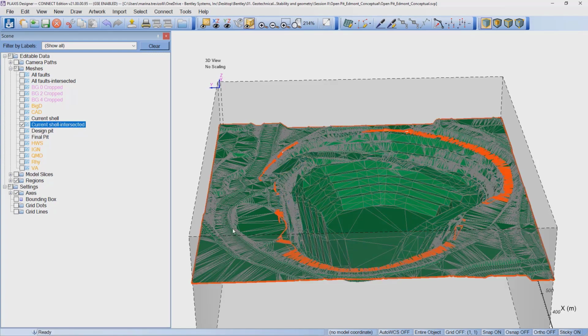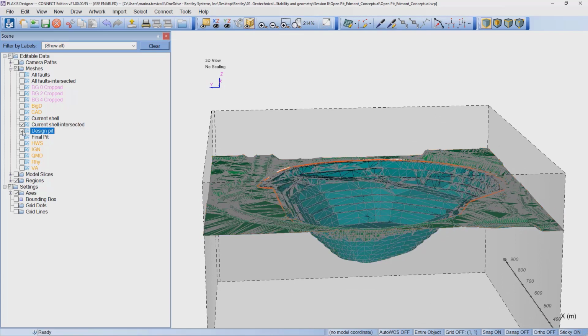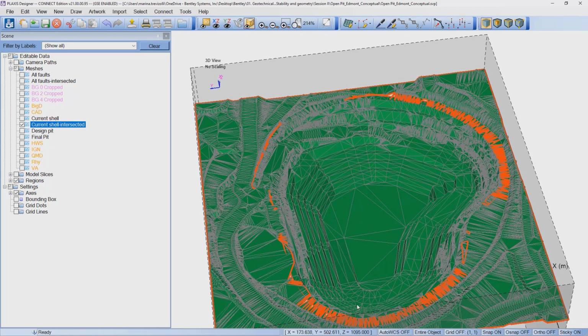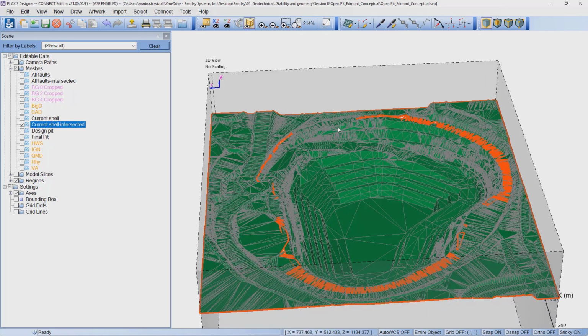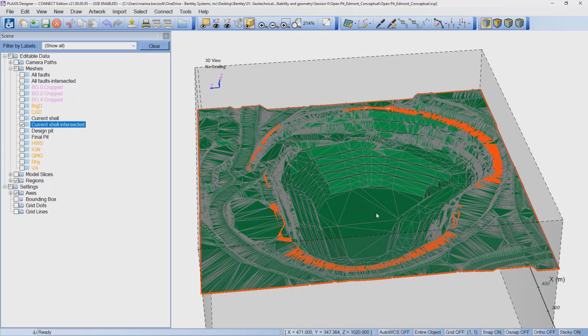And this new mesh would be intersected with the design one. So it's now respecting the elevation of the design. But we noticed that ideally we should have this orange line limiting only the extension of the surface. In this case, we're also obtaining some orange lines inside the intersecting points of both surfaces. And that's okay. This is something we can fix with the software as well. It may happen during the intersecting process, during the building process, and we must be aware of the possibilities we have to fix this.